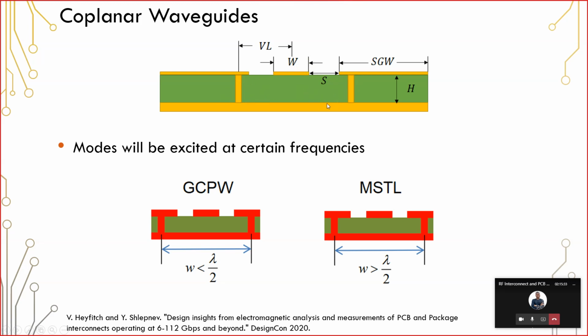And what does very big mean? Well, very big means a couple dozen millimeters. So it needs to get very large in order for this structure to have a large enough span between these vias in order to excite any kind of mode structure in here.